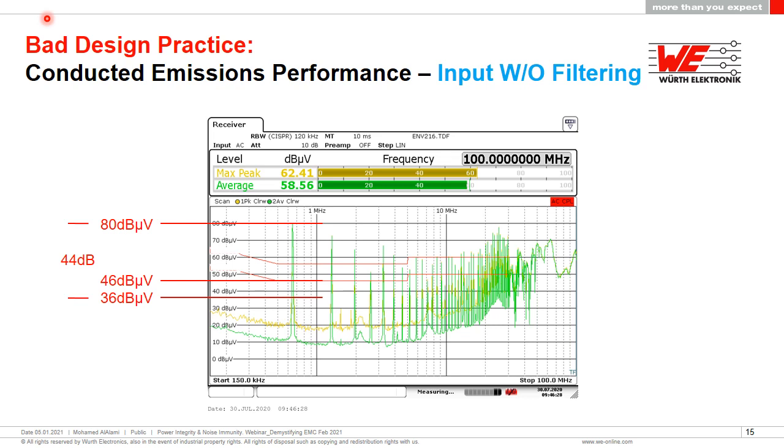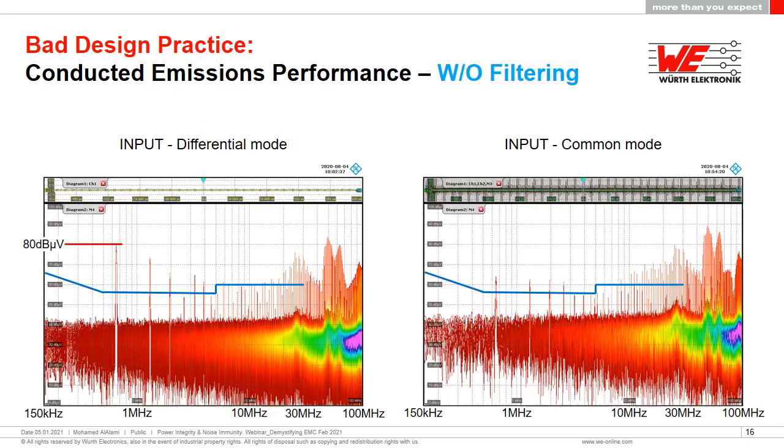Hence why I mentioned it's very important to get a decent scope when you're doing these measurements, if you're going to get a more realistic reflection of what's actually happening on the board, as opposed to it being pickup, or noise pickup. And that's where I think investing in a decent set of scope probes would be very useful in this case, because it also gives you that better understanding of what's going on on your system, on your board.